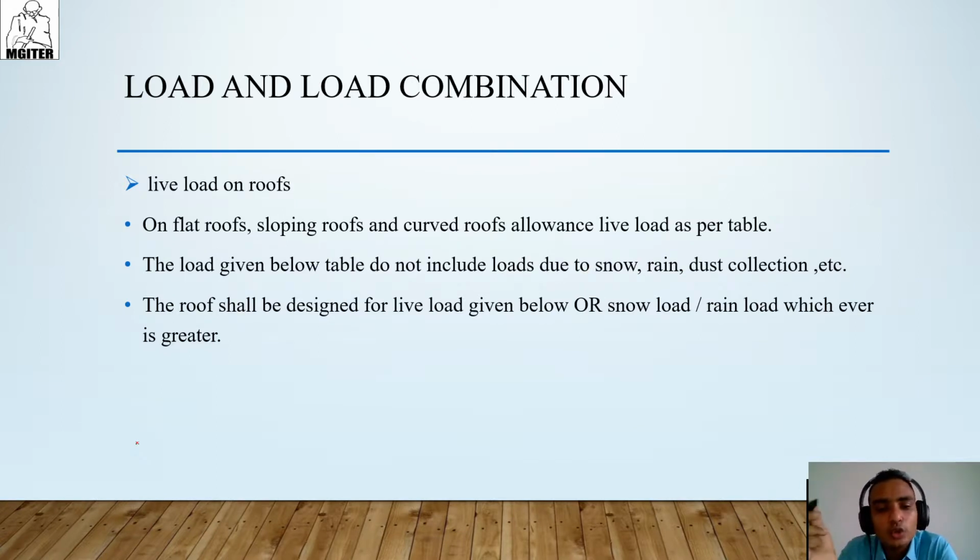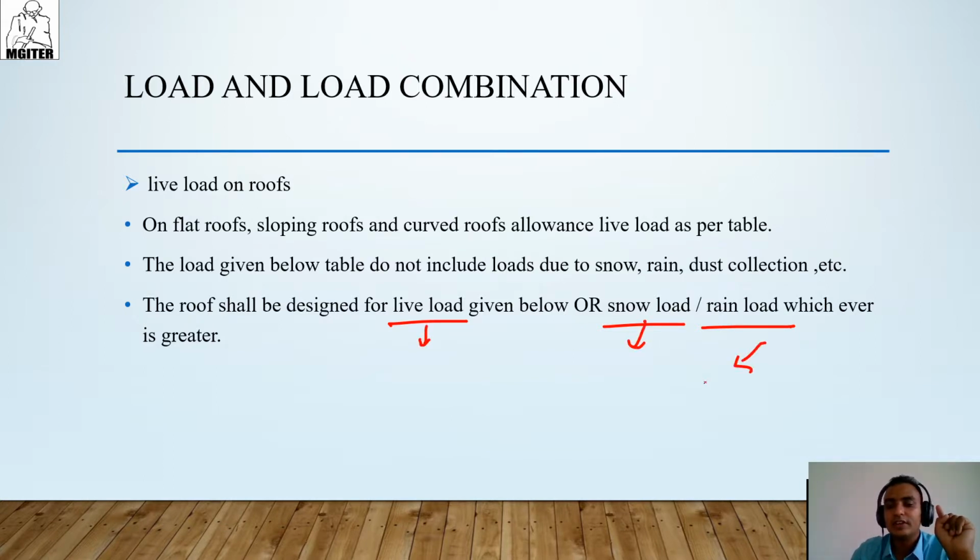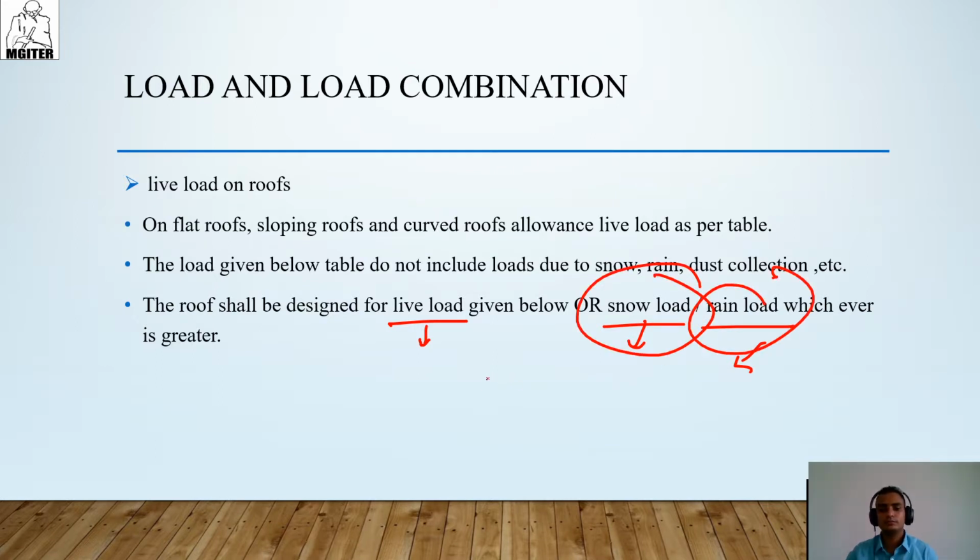While we are designing a roof, we calculate the live load as well as snow load and rain load, and whichever load is maximum among these values, we will take as the live load. We will design the roof by this load.